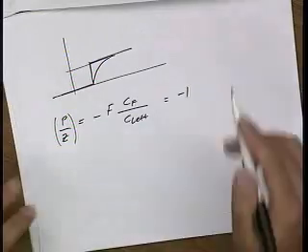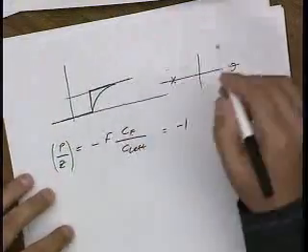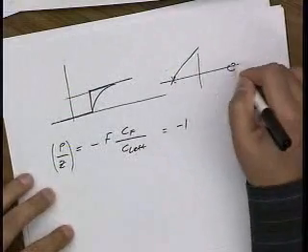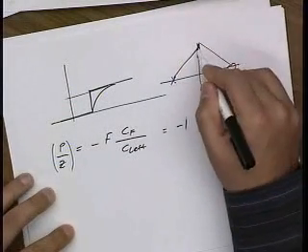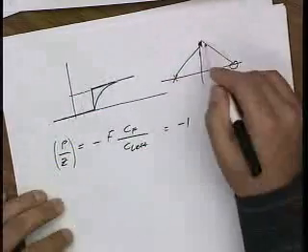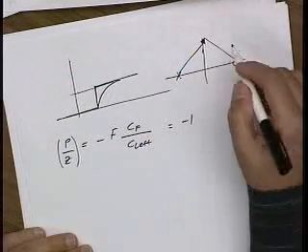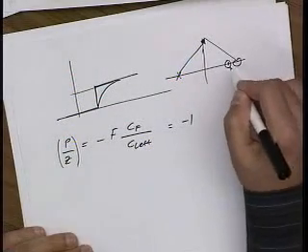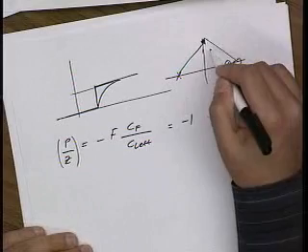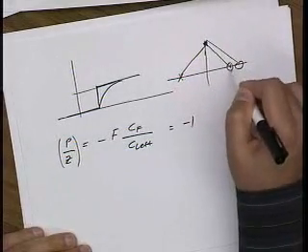This is not pole-zero cancellation. This is a pole here and a zero here, so that at any point on the j omega axis, my distance from the pole is the same as my distance from the zero, so it doesn't ever hurt me to see the pole. Well, what if this is slightly offset? Then these distances are not exactly the same, and I actually will feel the effect of my pole and zero.